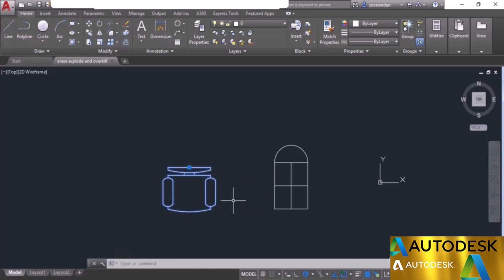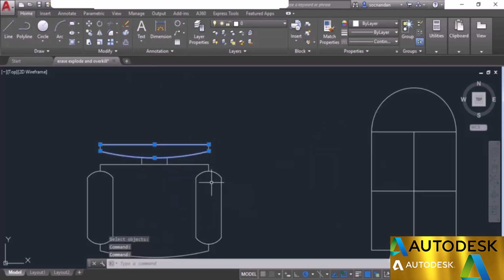In order to break it into different parts, simply select the explode tool, and here we have this explode tool. Select the explode tool, click on the object and press enter. And now move to this object, and you'll notice that now it has been reduced to its separate units. We can now select all of these objects separately, even though it was a block initially.